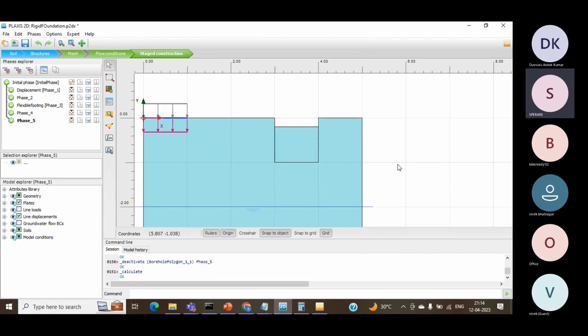Okay, that's where my guess got cleared. Based on that output, I see what displacement is happening, how much it was able to excavate, and then I move the solution forward to that particular phase. In the next step, again I can go for another 0.2 level of excavation. And if it is running fine, you are doing R&D, guys, so you can increase that 0.2 to 0.3 and then go.